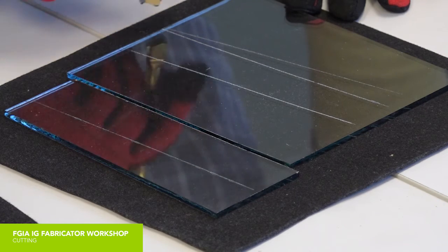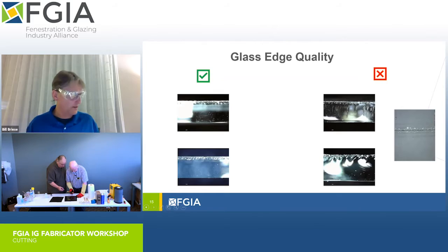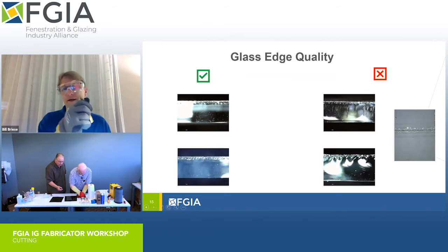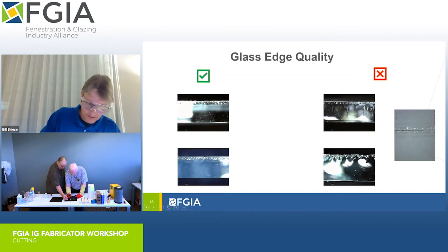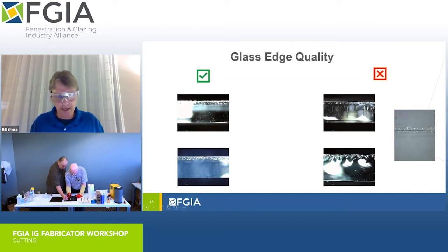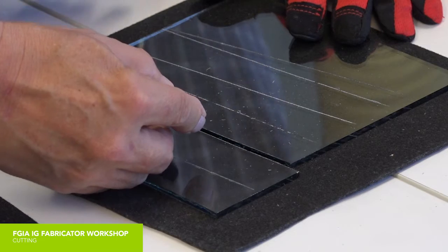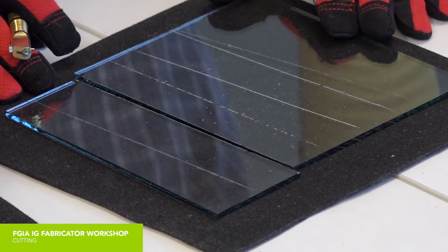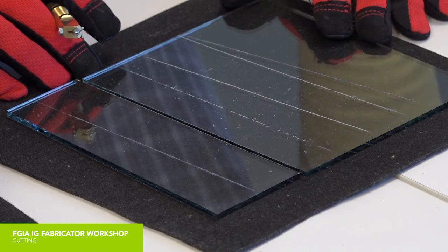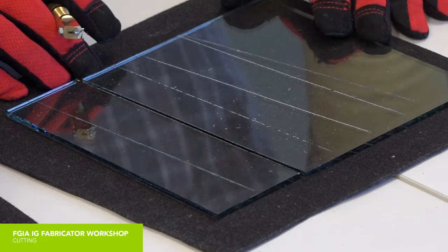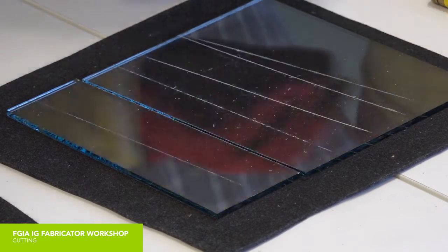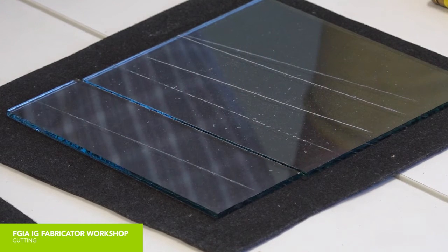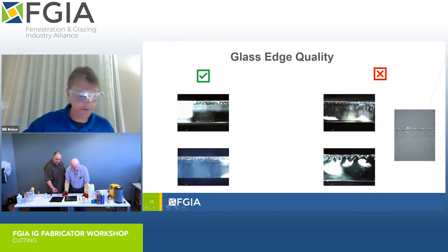But it's still blooming a little bit. It's still chalky a little bit. Why don't I try the 127, which is a little bit sharper. Wow, that one is incredibly difficult to see, but there is all kinds of flakes, and it's snapping and popping. Basically, that sharp angle is directing all that force straight outward, and the glass is not strong enough at the surface, and it's causing all of these slivers.